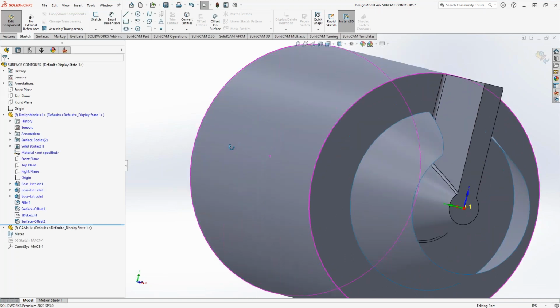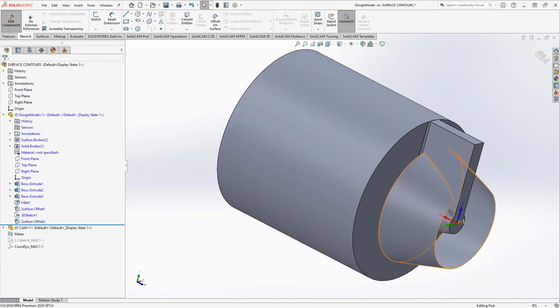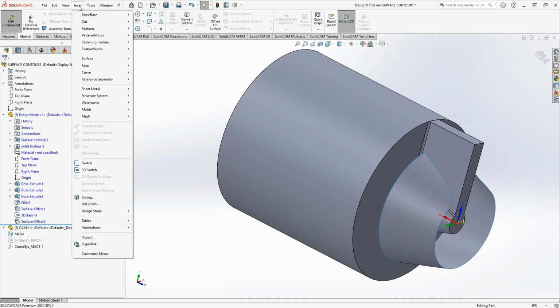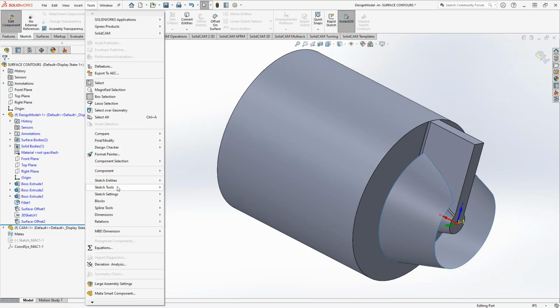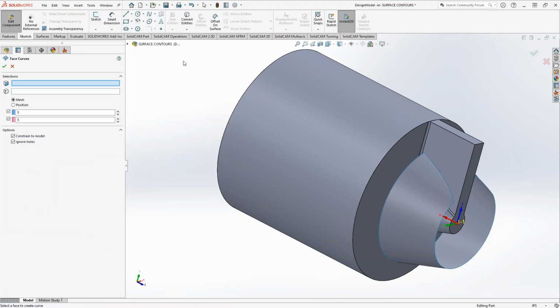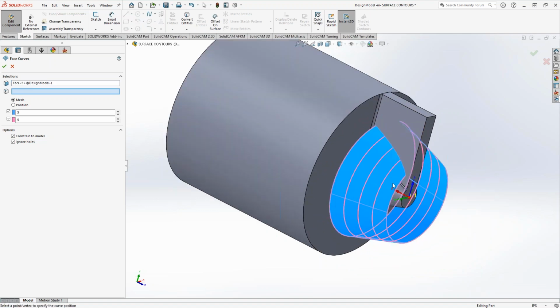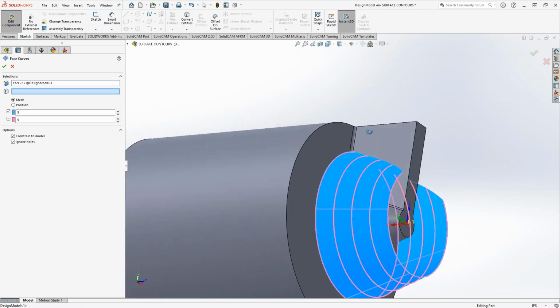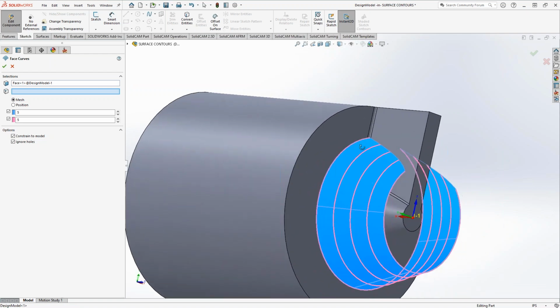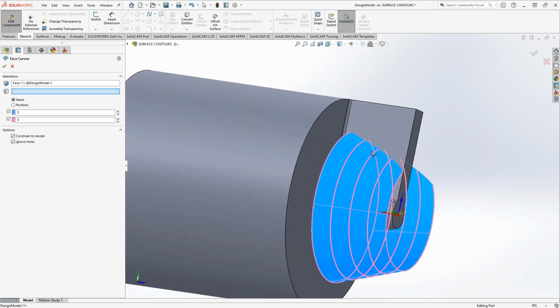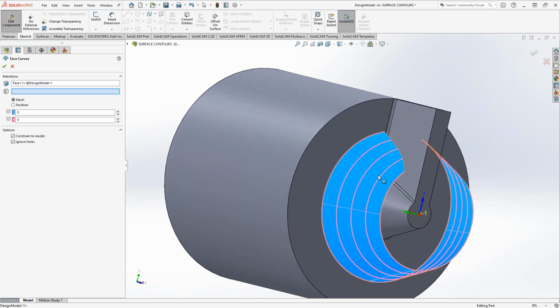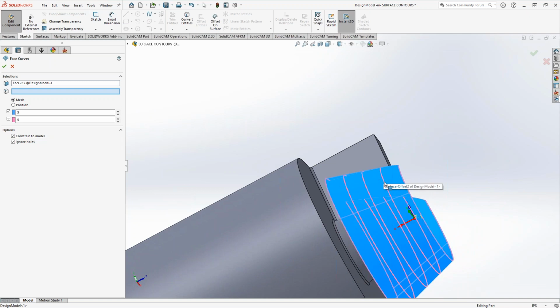Another thing that I usually use for curves on a surface that might be helpful is not usually up here. I usually have to go to Insert, Tools, Sketch Tools, Face Curves. Now this is one that some people use more than the other one that I showed you. You just choose the surface, and then you can see that it's adding curves there that are in the direction of, I believe, Kevin, would you say these are in the isoline direction? I'm not sure how to describe this, but you can kind of see that the pink lines follow the curved surface of it.